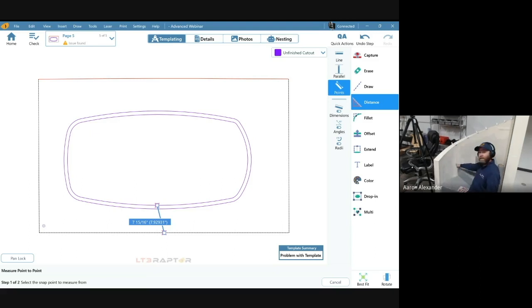Maybe you look at it right here, and that consistent radius you drew is like a 1/4 inch off from what you scribed. I don't really like that. Let's go ahead and erase that arc, undo. Let's undo that arc, and let's pick point number 4, point number 18, and point 28, and redraw it.